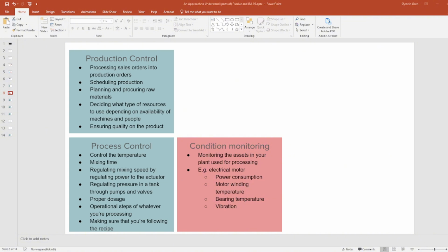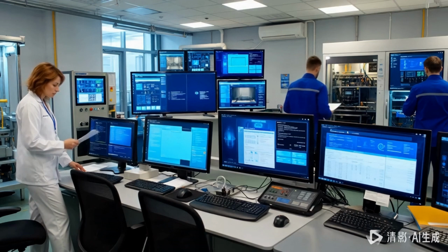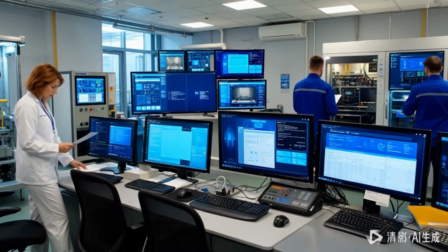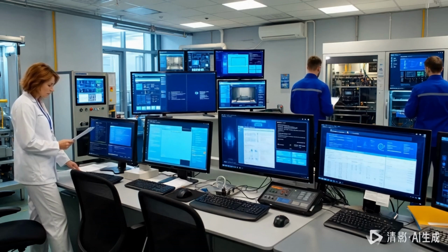And although these alarms would probably be supported by the same controller and same supervisory system, and even in the same alarm view, the stakeholders would typically be different people. Issues with assets would probably have to be addressed by maintenance, and if it's persistent, it could be addressed by engineering. And issues with products and production would be more relevant for the area responsible and/or the quality manager.